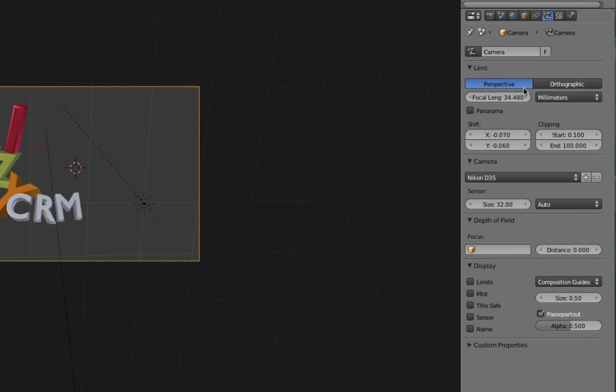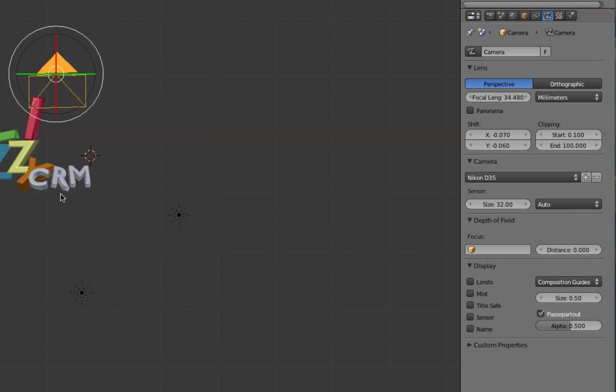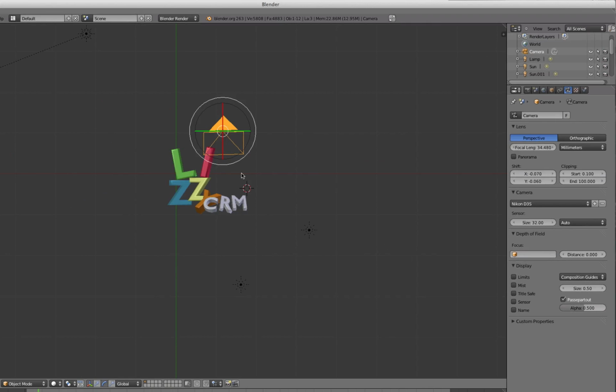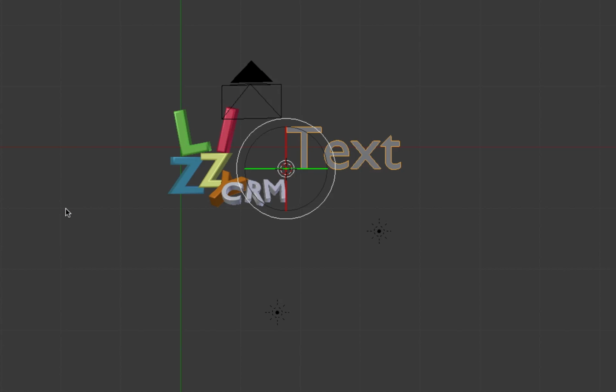So once we get that done, again, I can hit F7, get back over here. All I did to create this image is I laid some text objects. So if I hit Shift A, it'll bring up our menu, and I just told it to enter a text object. Now by default, it puts it on here and it already has the word text in it. So if I hit the Tab key, back up, and say I want another L, I hit L, I hit the Tab key again to get out of there.